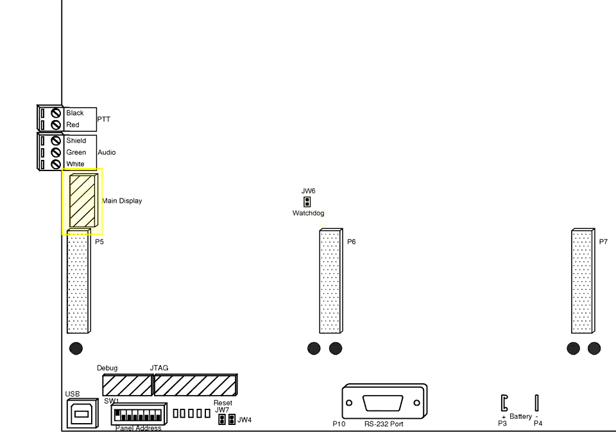Above P5, you will see a smaller ribbon cable connector that is allocated for the QX Mini main display. The connector is keyed, so you do not install the ribbon cable backwards, causing any damage. Finally, the 2 terminals left are the audio and PTT, or push-to-talk inputs, from the microphone connected to the QX Mini master panel. For the QX Mini BP booster panels, the main display ribbon connector and audio and PTT terminals are not used, as there is no user interface on the booster panel.